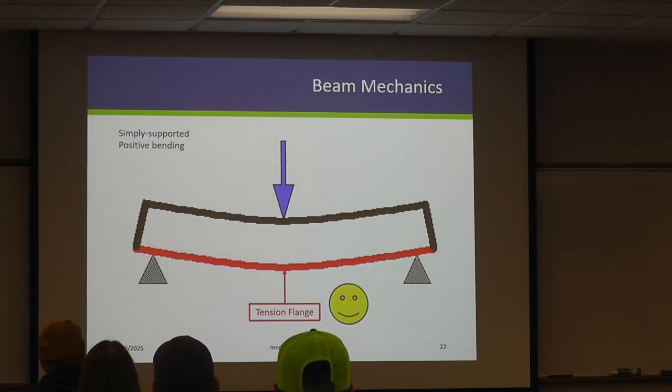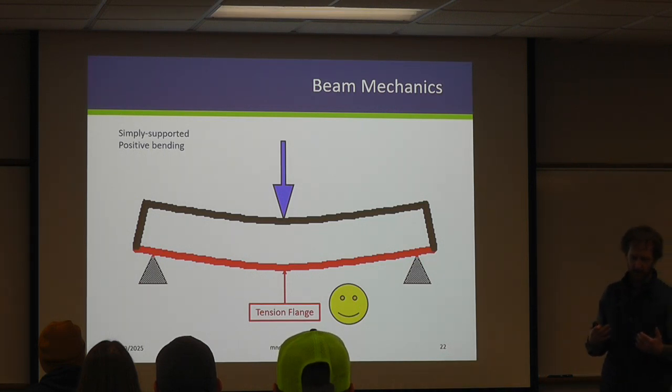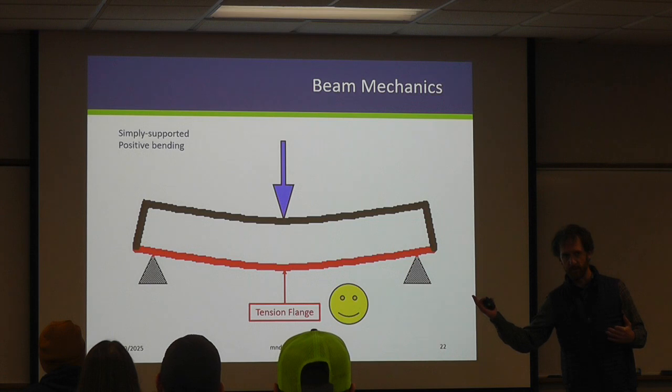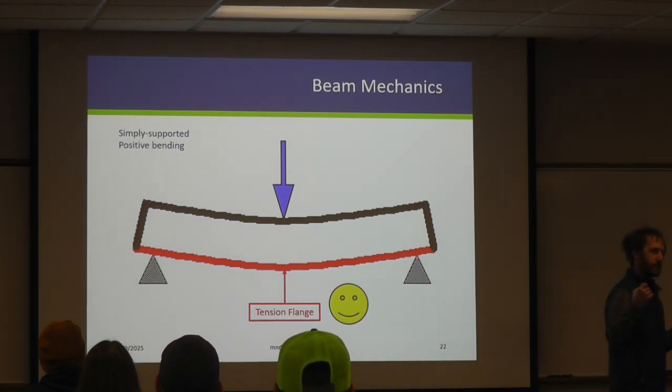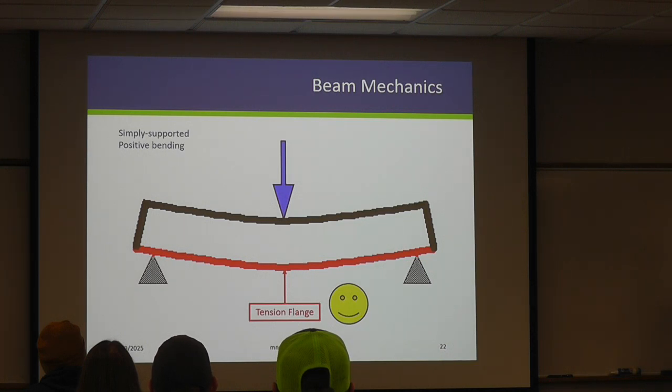So I talked about, real briefly, a continuous steel system. Let's take a step back and think about what that really means. The photo here would be what's called a simple span. This is what all pre-stressed beams are in Minnesota, meaning that at your bearing points or at your substructure, there's going to be a physical break between the beam for the next span.